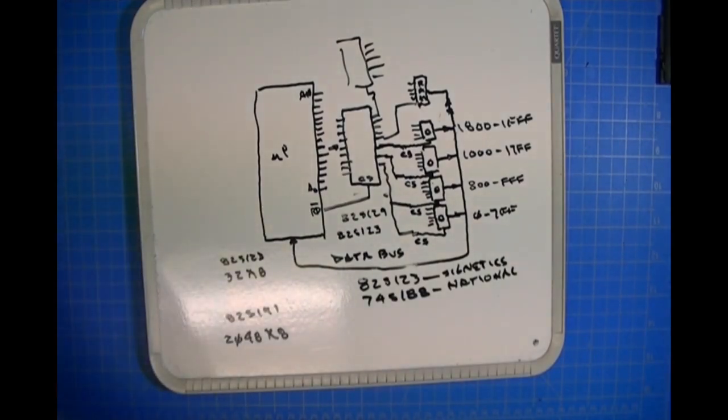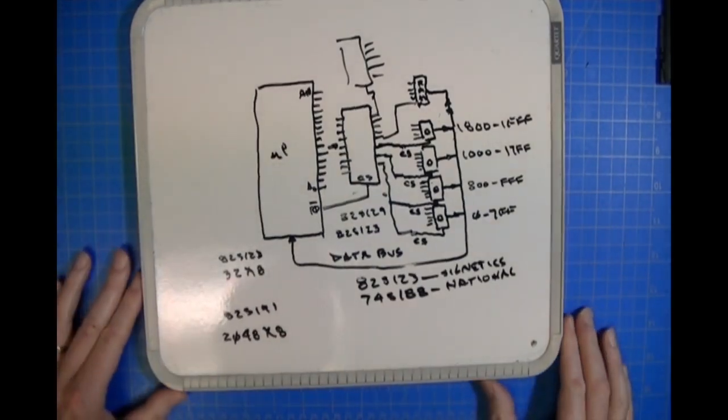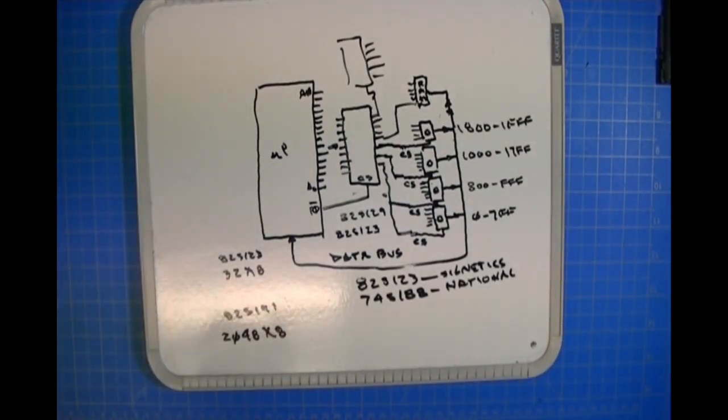And when you program a bipolar prom, unlike an MOS device or an EPROM where you're putting charge on a floating gate by applying a reasonably large voltage, meaning 12.5, 21, 25, and that'll put the charge on the floating gate of the MOS transistor.